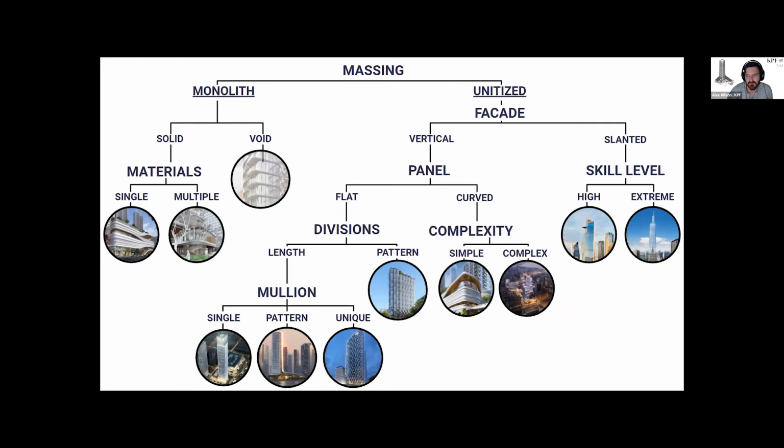We have a project which is confidential within the office that uses Rhino.Inside to create voids, and then they cut walls. Like we've talked about, it's about using software for what it's good at. If you have a wall within Revit, you have all of the positive aspects of using Revit walls, for example, the fact that you can change the structure, and it'll cut well in plan.